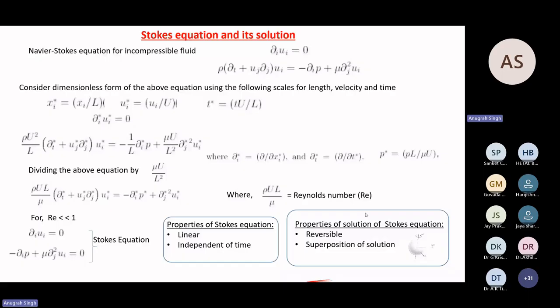Now coming to our formulation for dense particle suspension rheology. I told you it builds from the single-particle equation, and we assume that Stokes law is valid. We will see what the implications of Stokes law are. Now, the Navier-Stokes equation for an incompressible fluid: this is your continuity equation, mass balance, and this is the momentum balance. We all know that. Again, it is in index notation. Those who are not familiar, kindly read any book like G.K. Batchelor's Introduction to Fluid Mechanics.